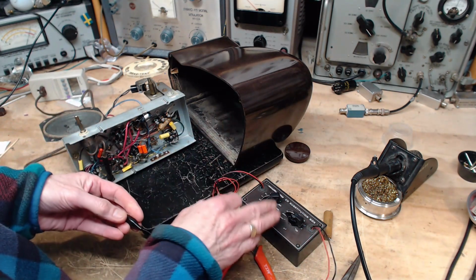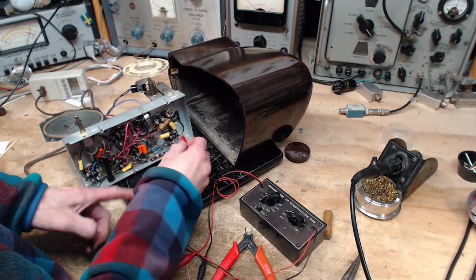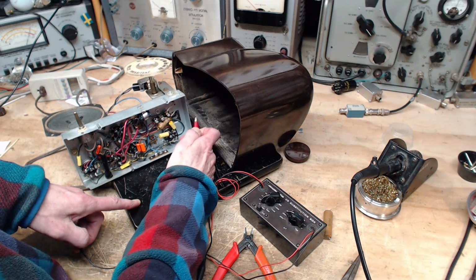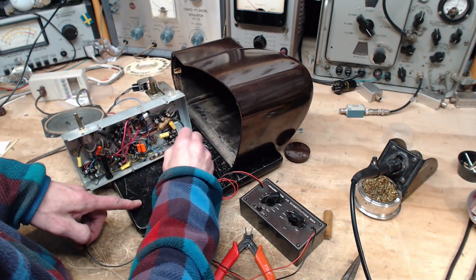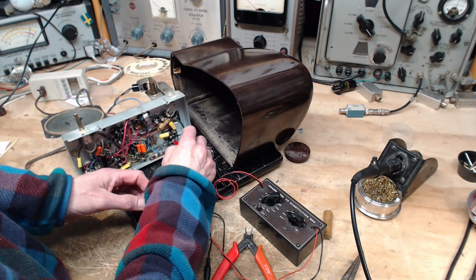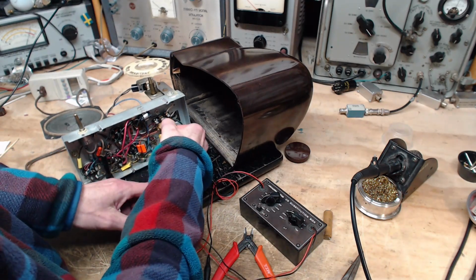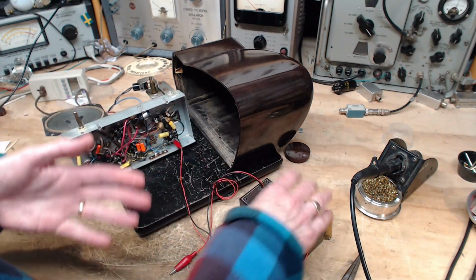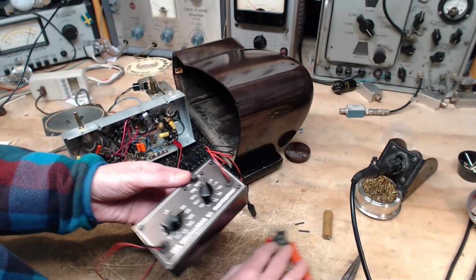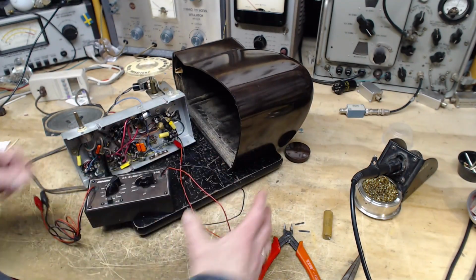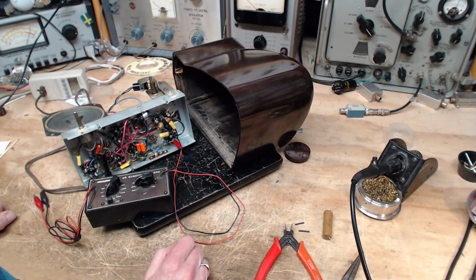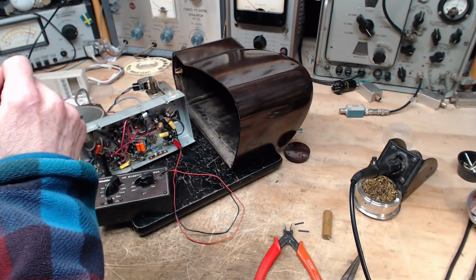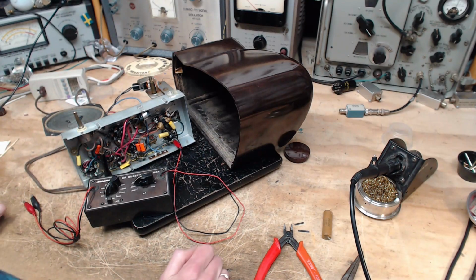So I'm just going to put this in parallel with the capacitor. This is the one I just installed. I can leave this capacitor in while I'm doing this. It's a small capacitor, so I'm paralleling in another capacitor. It would just add to the capacitance value. Okay, hopefully we can pick up a station. Yeah, I have to use this antenna just to get the radio tuned. Okay, ready. Here we go. Away we go.